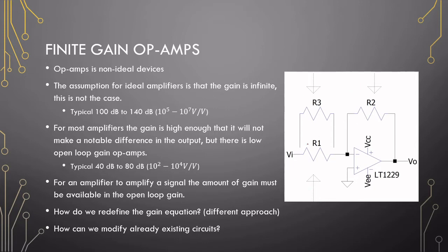So in the figure here on the side, to answer this question, we will do this in the simulations as well and the problems. If a circuit is already on a board, you can modify resistor 1 by soldering an extra resistor on top of it in parallel to fix the gain, because if you decrease resistor 1's size, the gain will increase.